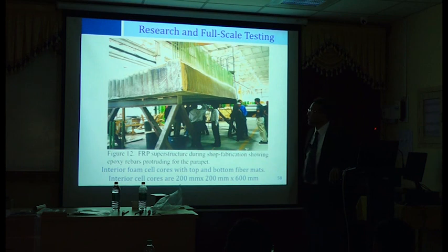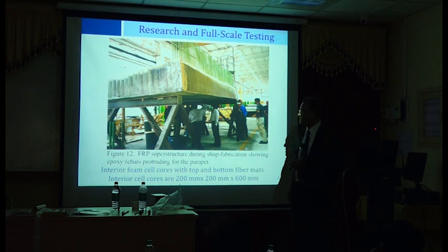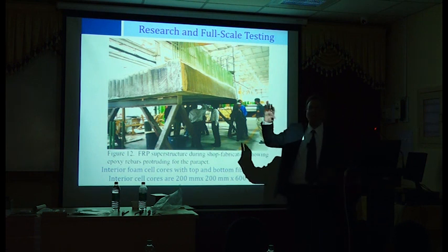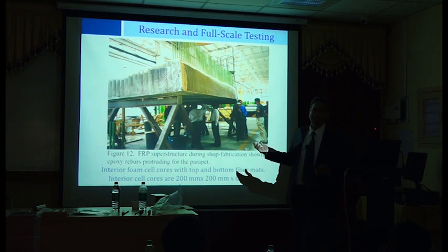But in any new product, you must do full-scale structural tests. That's another thing which is difficult in India, in the sense, except for a few major institutions like IIT Madras and Structural Engineering Research Institute in Madras, places like that, you really don't have very large testing facilities. And testing this kind of stuff is very expensive. So that's something you have to consider. Before you use them in practice, you really have to test these members at full scale. Full scale, that's most important. Small scale is fine, but full scale is something that will really cover